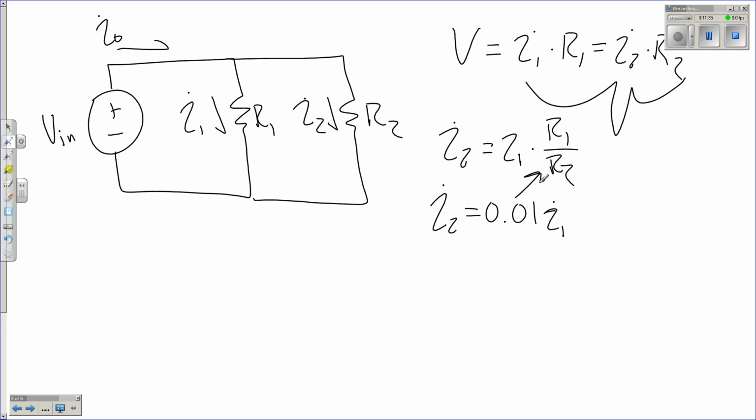So in this case, we can just pick what we want R1 and R2 to be, and the other will follow suit. Let's say R2 is 10 kilohms, what does R1 need to be? Or if we pick the opposite, we can say R2 is 1 kilohm. We have it in the notes. All we have to do is multiply that by 100.